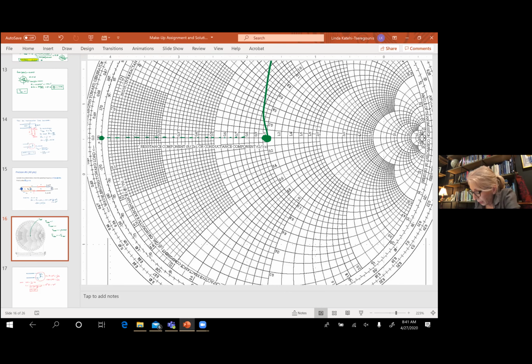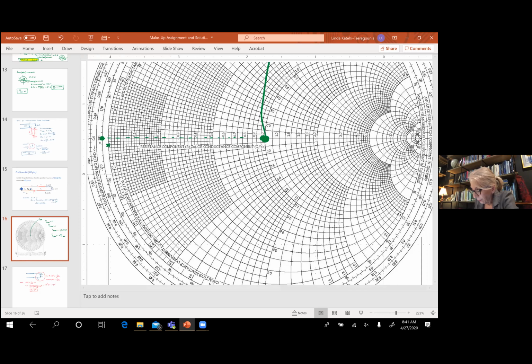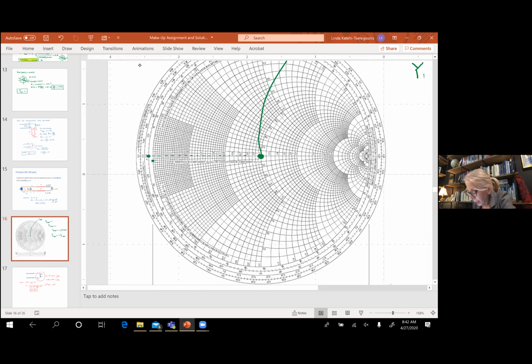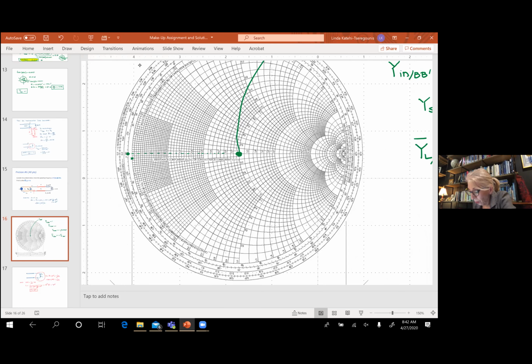Okay? And we will need to make sure that we move this until we go into 0 practically, but we cannot move for this small distance because it's too tiny. You can bring the capacitor and put it, but the stub is so short that you cannot even make it. So practically, I need to go to the next length of the stub that will be more practical to make and easier to fabricate.